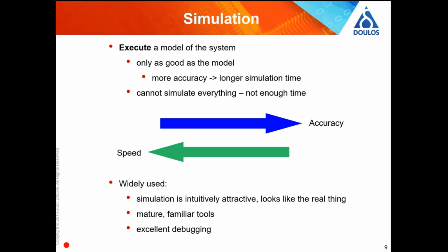So mainly what I'm going to be talking about in this talk, and the one I'm doing this afternoon, is what's called RTL simulation. So it's simulating the design that you actually type in. But you could simulate more abstract models, and I've done a lot of that. For a digital TV chip, you can't just design the details of millions of gates of DSP by writing RTL. You need something more abstract. We use C++. Similarly, you need to do more detailed simulations as well.